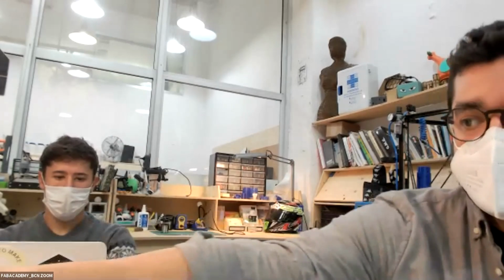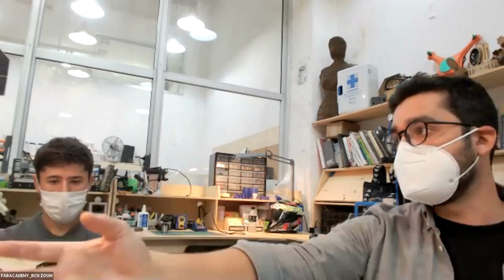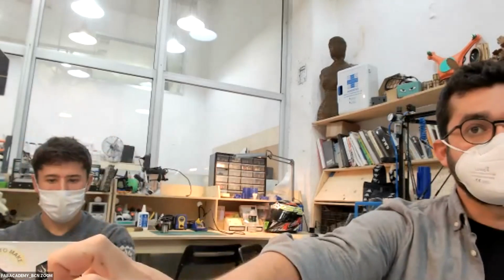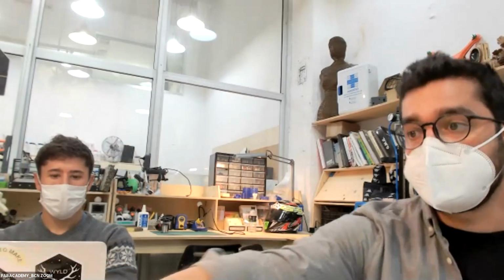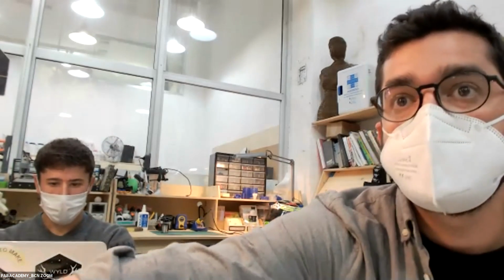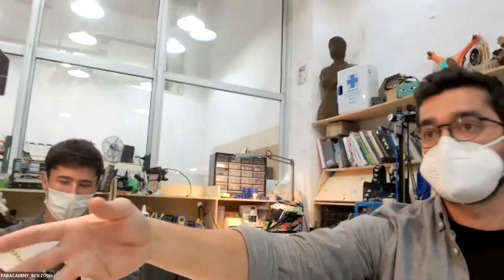So that's the basics. When you design machines, you have that trade-off. What you choose, and based on that, you start building on top. The size of the motors depends on the strength you want, etc. For example, for these small machines, do we need strength? Yes, but using the threaded rods automatically augments the strength that we apply with whatever motor. So actually, we can reduce the size of the motor because we don't need that huge motor for such a small machine. We can put a way bigger motor in this one. Yes, in that case, basically what we are doing is upgrading. Now we can cut steel because it has more torque.